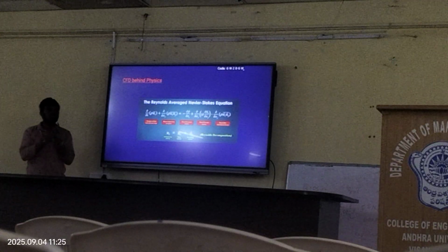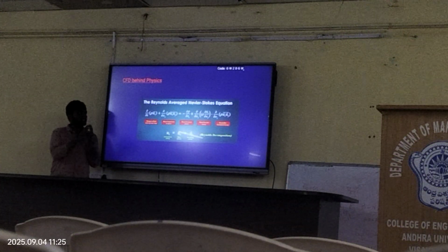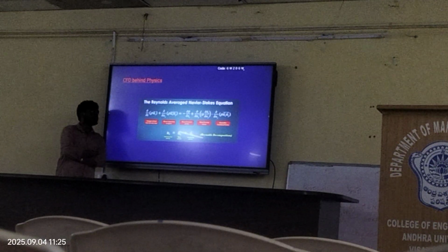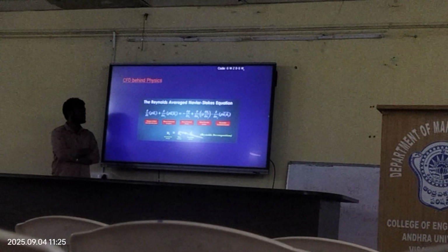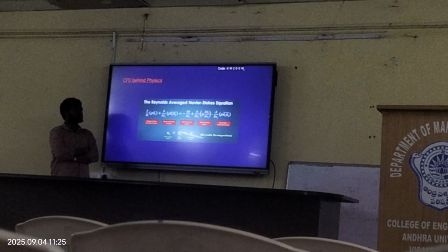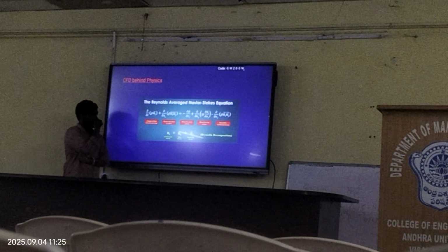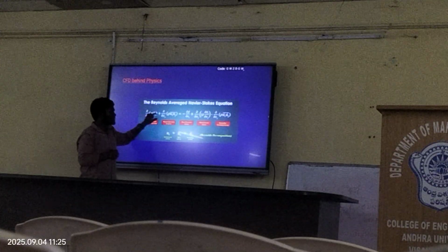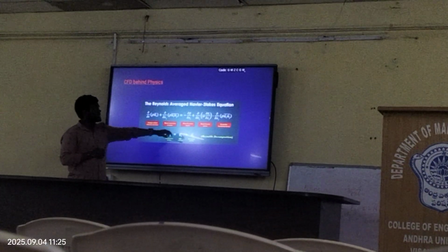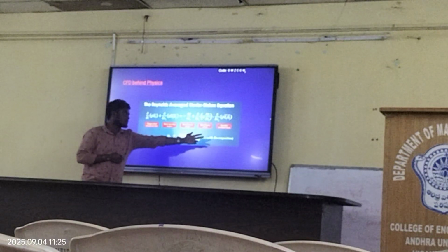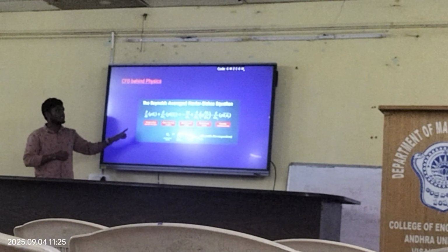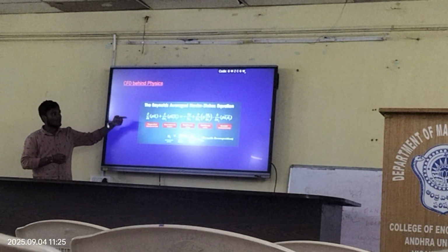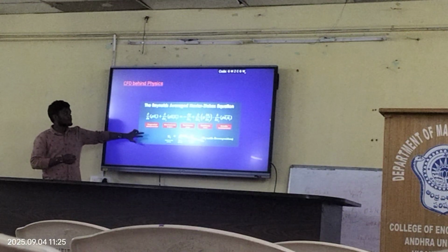So, the physics behind CFD. Generally, the Reynolds equation is very useful for us in fluid mechanics and in resistance and propulsion, etc. But the Reynolds averaged Navier-Stokes equation also uses the fluctuating components very finely. As we can see here, the change in fluid velocity over time is depicted by this term, and this is the mean convection in space, and this gives pressure, viscous stress, and Reynolds or turbulent stress. This equation is mainly used in CFD. Actually, the system behind computes this equation with a number of iterations for each and every step, and then gives the result.